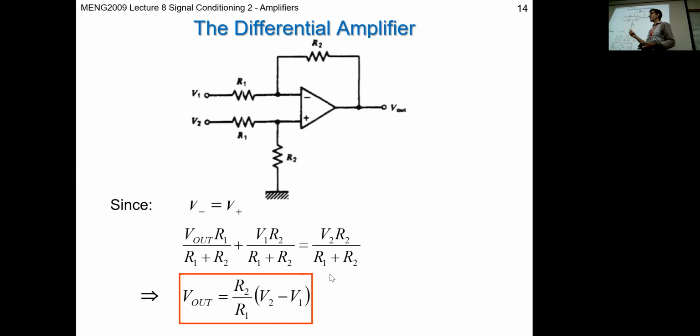That could be problematic because one is tricky, you actually have to change them out. But also every resistor is slightly different. So even though they're nominally identical, with the identical resistance, in reality you do have manufacturing variability in all electronics. So they're going to be slightly different, and that'll be a source of uncertainty in the amplification of your diff amp.